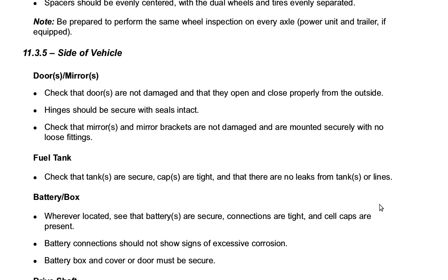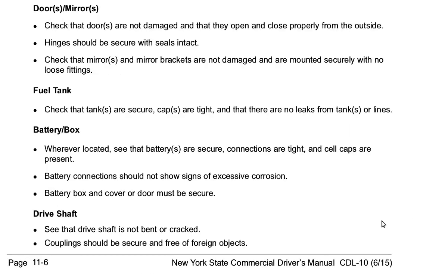Wherever located, see that the battery or batteries are secure. Connections are tight and cell caps are present. Battery connections should not show signs of excessive corrosion. Battery box and cover or door must be secure.